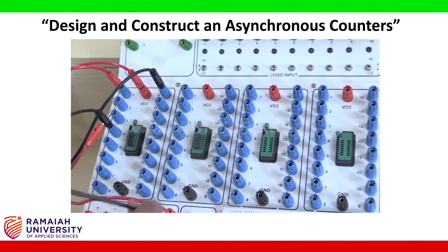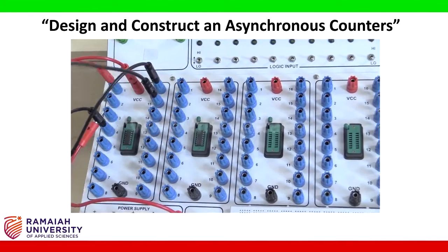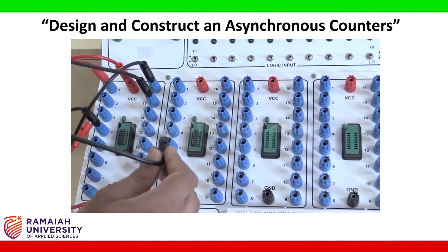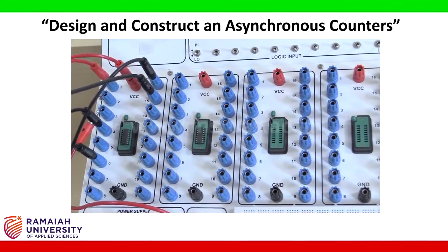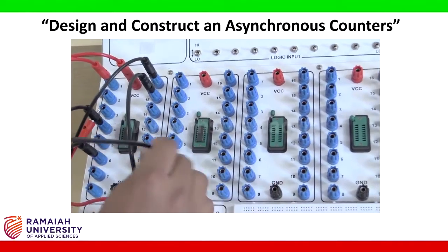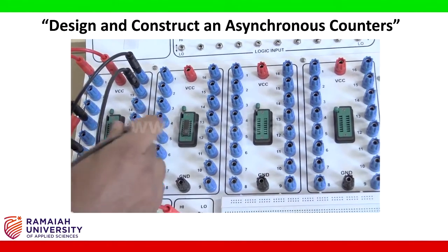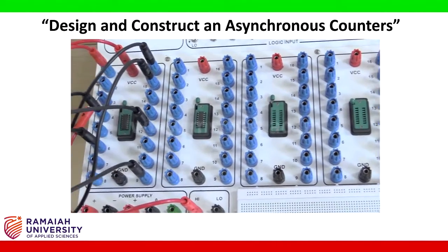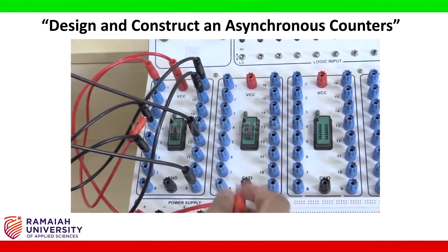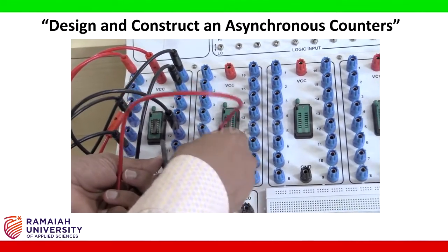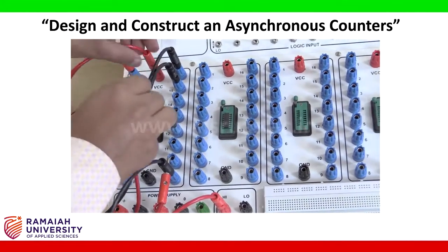Then pin number 15 is connected to pin number 6, and pin number 9 and 12 are shorted, and from that you have to connect to VCC, that is here.